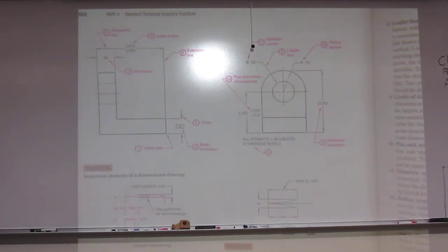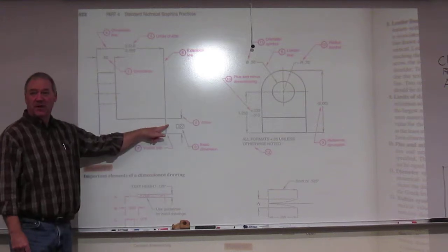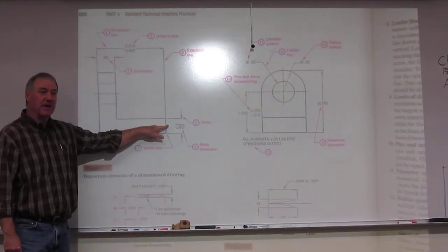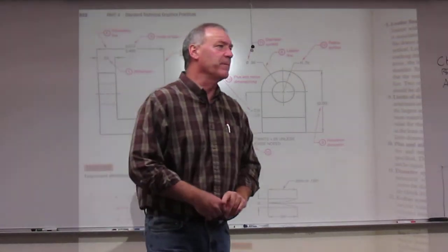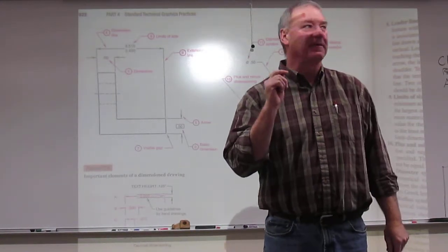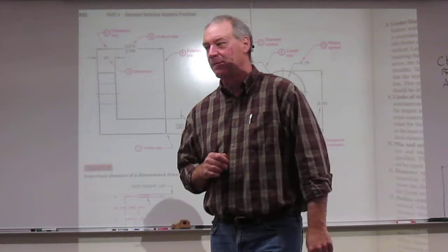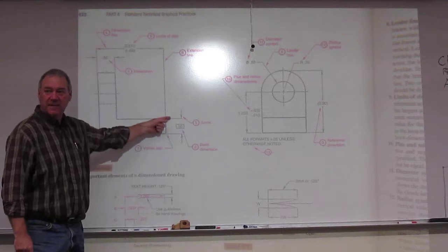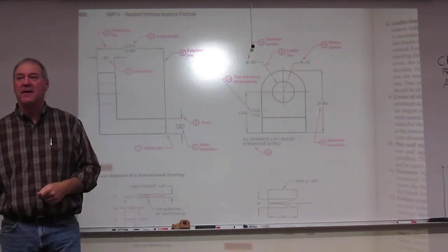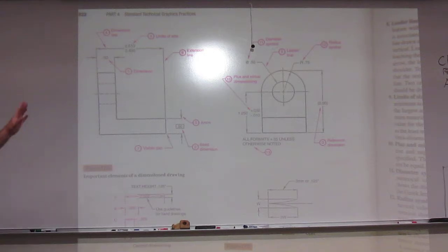And so that's what they'll do, is they'll slow down at that point, and they'll realize that everything is kind of related to that. You rarely have more than one of these on a drawing. You can have up to 3. Well, actually, you can have more than 3, but typically you'll rarely see more than 3. Why would I have 3 of them? Keep in mind, it's a theoretical perfect dimension. Yeah, for our 3 dimensions, right? This would be a height, basic dimension. We could have a width, we could have a depth. And we could have more than that, but that's getting into very specific items. So a basic dimension, a theoretical perfect dimension.